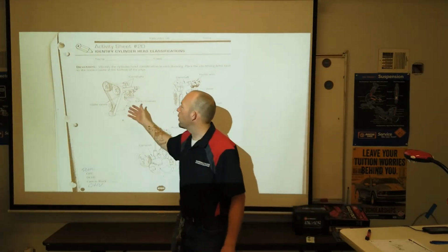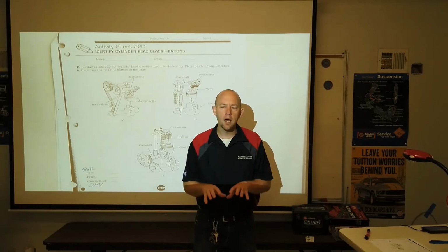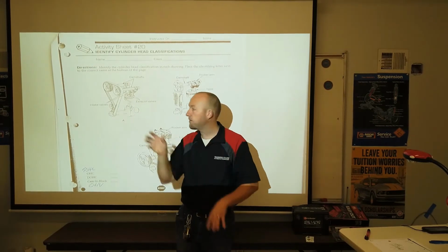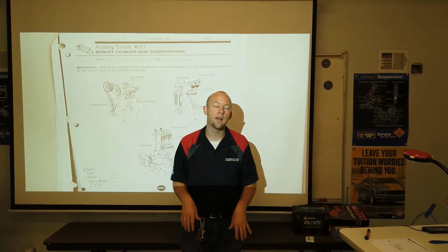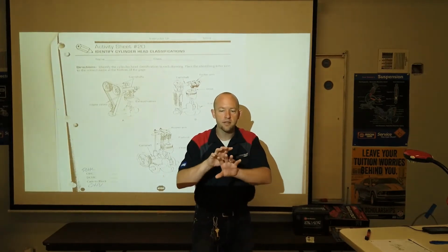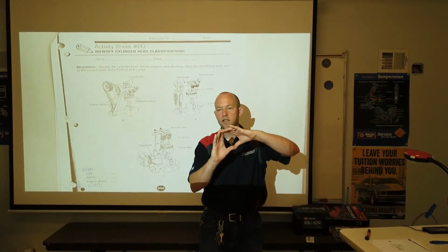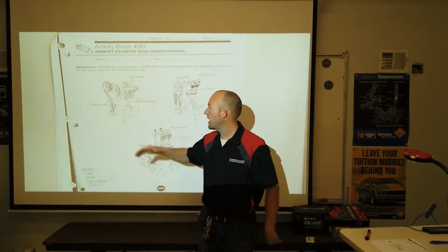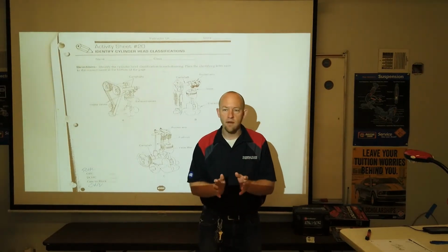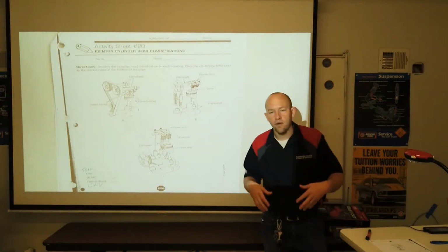This is also what led to the advent of variable valve timing, where they can change the sprockets on here and accommodate one that is not fixed like those, but that can be re-indexed to the camshaft. They use hydraulics, or oil pressure, to do that, because fluids don't compress. So they'll have a chamber inside that sprocket where they can re-index it by filling the chamber with oil, and once they fill it with oil, it's fixed and solid, and they can change the valve timing. If they want the exhaust valve to open a little sooner, they can advance that cam. If they want the intake valve to stay open longer, they can advance that cam. So that provides what we see with variable valve timing in that regard.